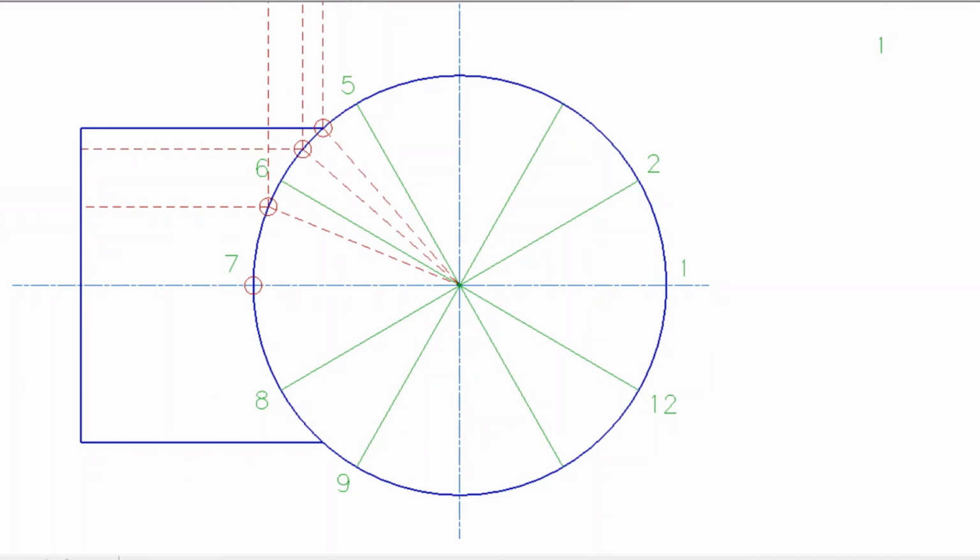Now, normally, guys, what you would do in the exam is number the points. Obviously we're not going to start by cutting it open here. We can cut it on the far side because you want the hole to be in the middle. So I'm going to cut it here, 1. You can go clockwise or anti-clockwise. I went anti-clockwise round, so 3, 4, 5. Right up to 5, we're not actually going to have a penetration point. We're only going to have 2 penetration points between 5 and 6.